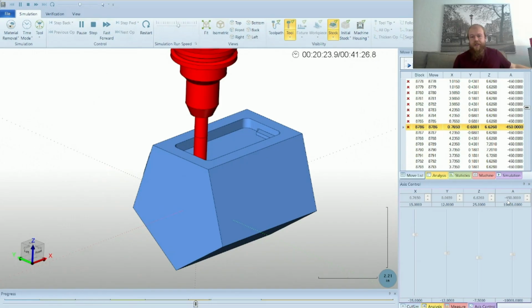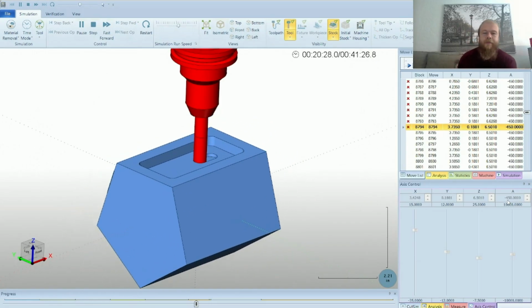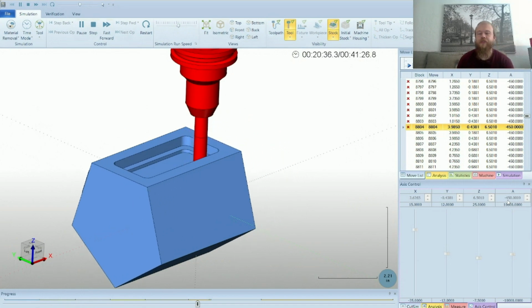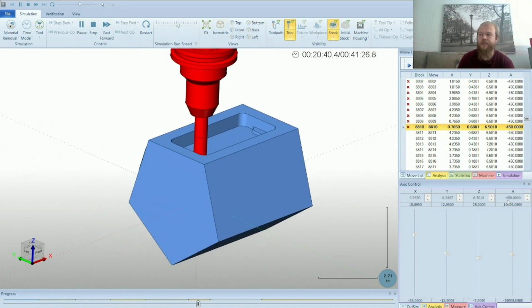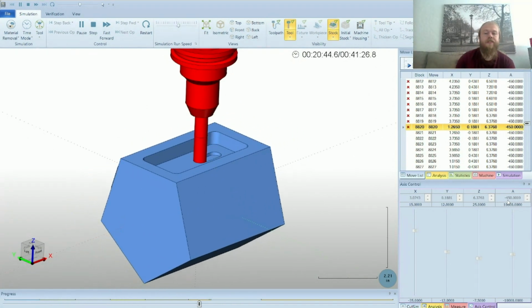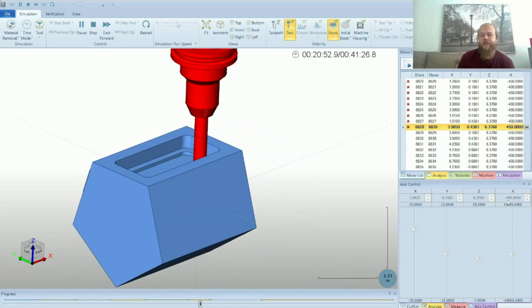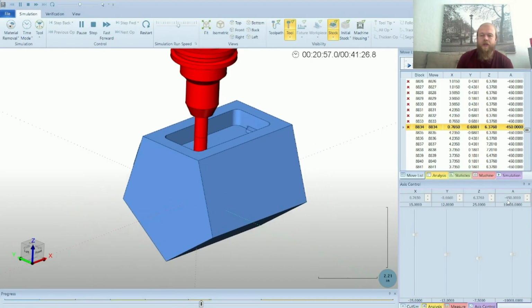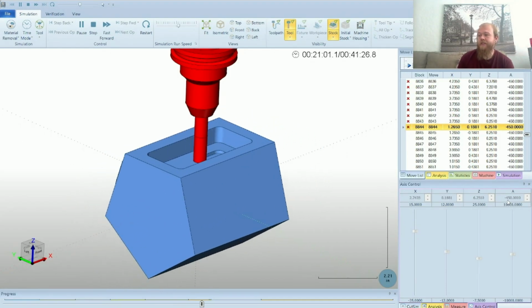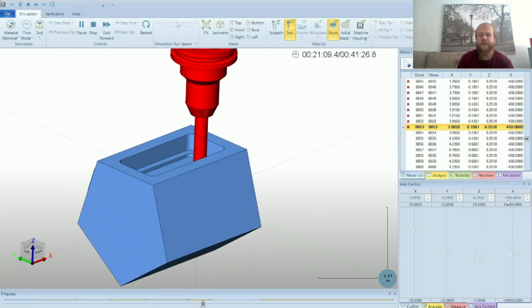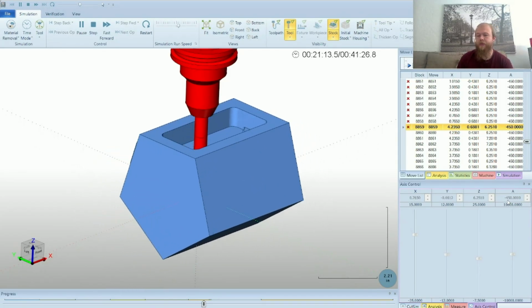Or minus 120, actually. But yeah, depending on your machine, it'll output the A-axis rotation coordinates specific to what you need. If you don't already have a machine and post-processor for your 4-axis machine, you can go to the page that you're on now, bobcatsupport.com, and under the post-processor tab, you can request a new post-processor.